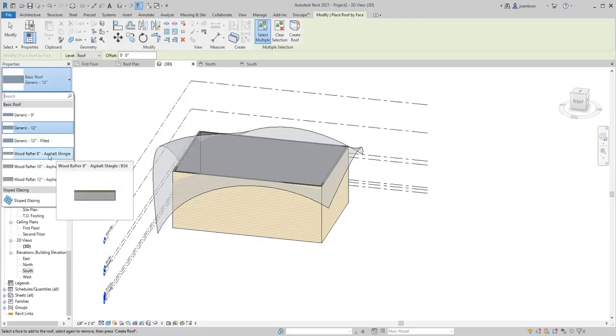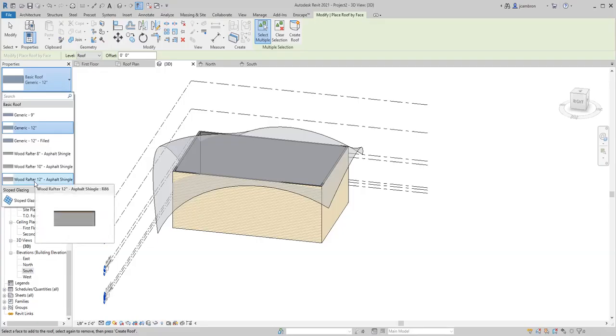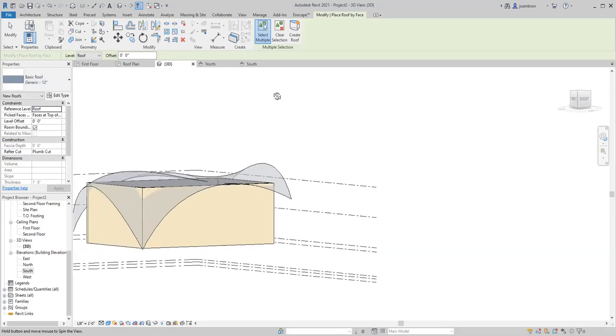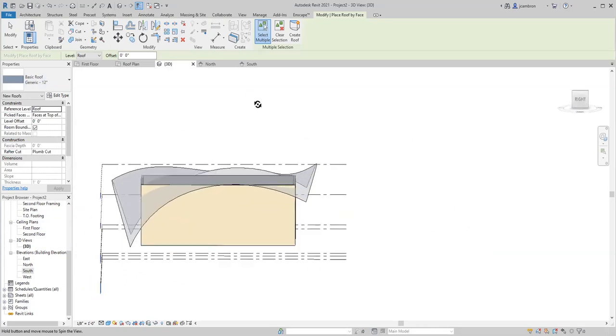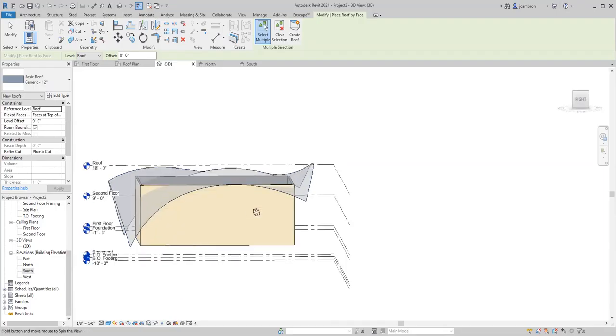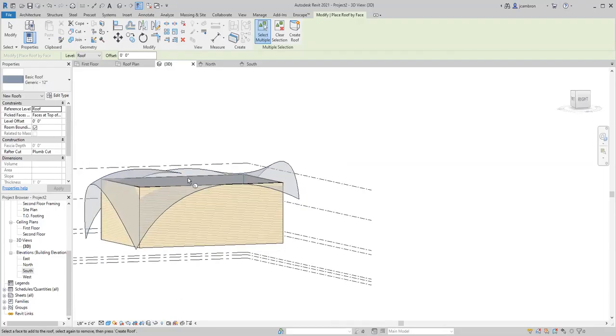Okay, you want to go as small or as thin as possible when you're doing something really crazy like this, because the thicker the roof gets, the more likely you're going to begin to have geometry running into itself. It's kind of hard to show here, but it could be where it dips down right in the center.